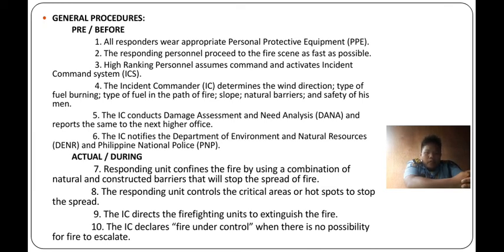The responding unit controls the critical areas or hot spots to stop the spread. 9. The IC directs the firefighting units to extinguish the fire. 10. The IC declares fire under control when there is no possibility for it to escalate.